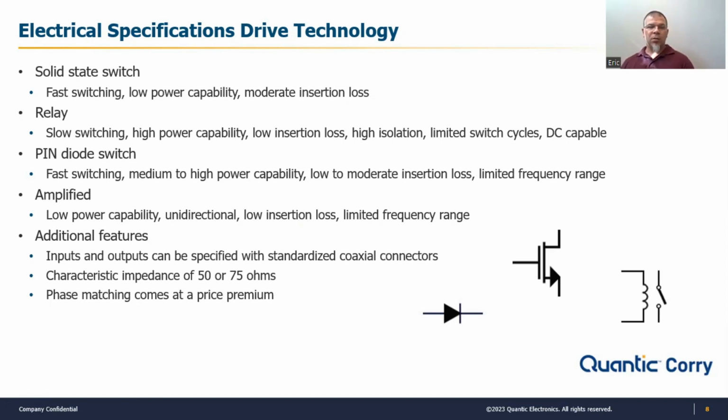And you would choose one over the other for various reasons. Solid state switch tends to be quite fast in switching speed, just as fast as a pin diode switch, but there are pros and cons to having both of those. A pin diode switch is much more expensive than a solid state switch, for instance.